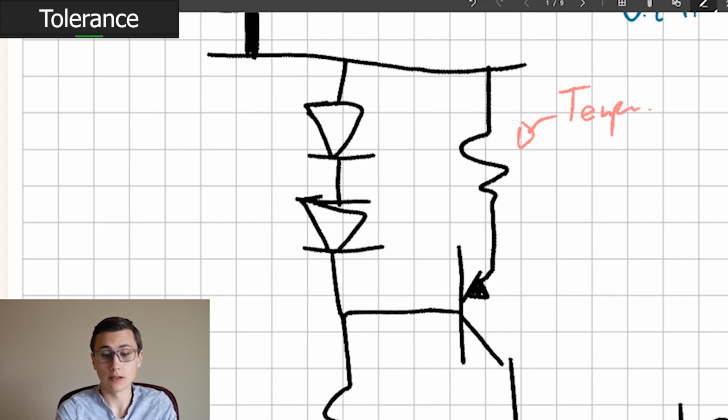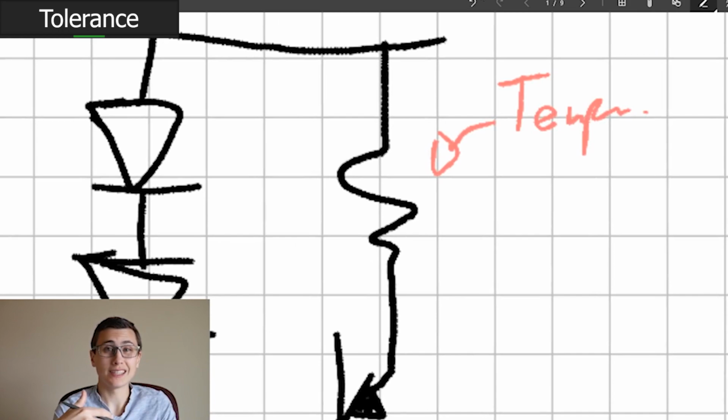Every resistor is rated with a temperature coefficient, and that basically tells you how much the resistor value will change for every degree Celsius. 100 ppm is pretty common, so that's parts per million, or for every degree that the temperature changes, the resistor will change by 100 millionths of its value, or percent, I forget. But look it up, it's in the data sheet. They give units, they give assumptions. It is very plainly laid out in English how that will change. They depend on temperature.